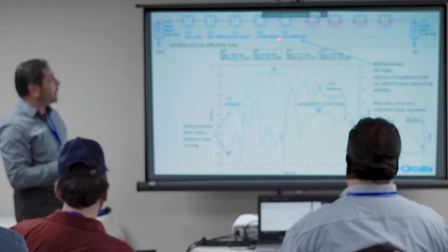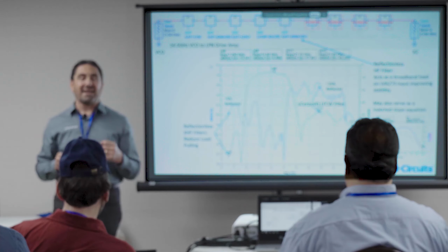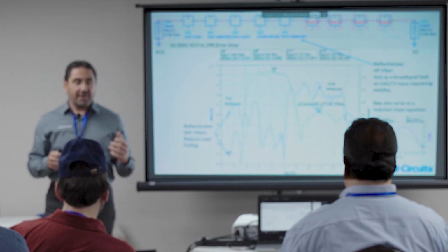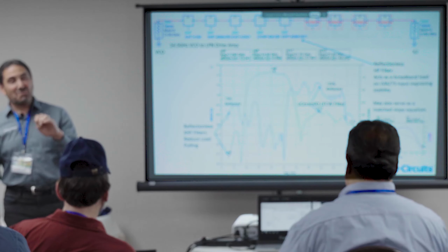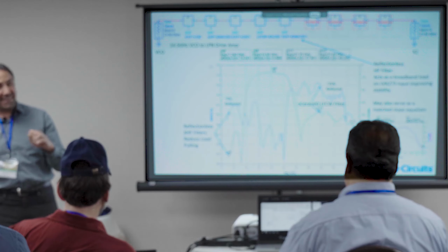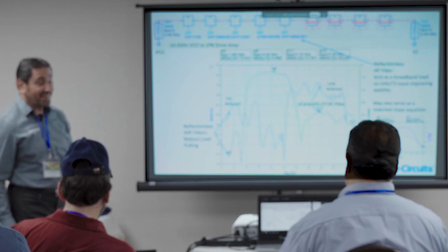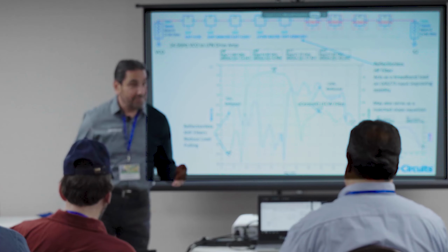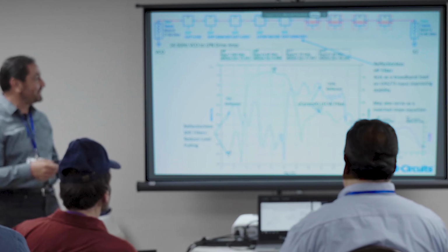Why do you put that on the output? Well, because it's in front of this LNA. It's in front of this very broadband amplifier. Now, do I want to test the unconditional stability of my amplifiers by presenting basically a 0 dB return loss on the input? Yeah, I'd rather not. I'd rather not test something like that in a system I need to deliver.